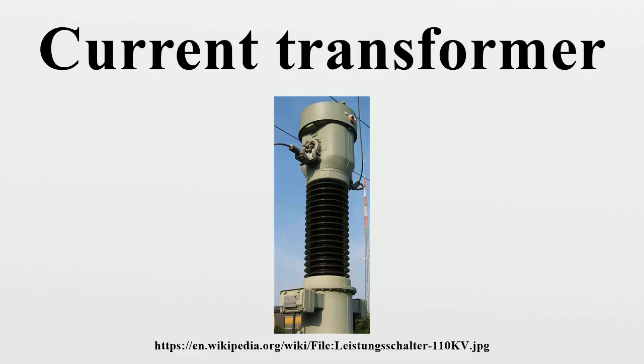This ratio can also be used to find the impedance or voltage on one side of the transformer, given the appropriate value at the other side. For the 4000-5 CT, the secondary impedance can be found as ZS equals N ZP equals 800 ZP, and the secondary voltage can be found as VS equals N VP equals 800 VP.